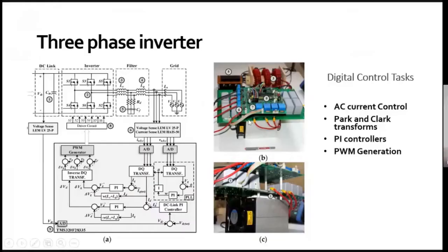And here, this three-phase inverter is exactly similar to single phase. The only difference is that in single phase, there will be a current injection algorithm directly. That means it can be direct injection or another transformed mode. In a three-phase inverter, all these things are converted into DC equivalents. That means there will be Park and Clarke transforms to convert the three-phase components into equivalent DC values.